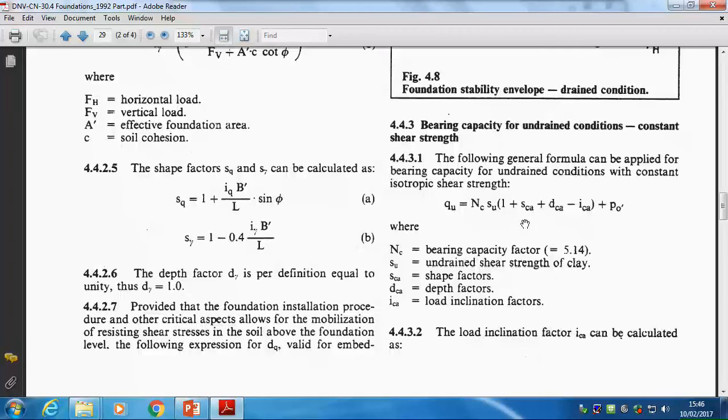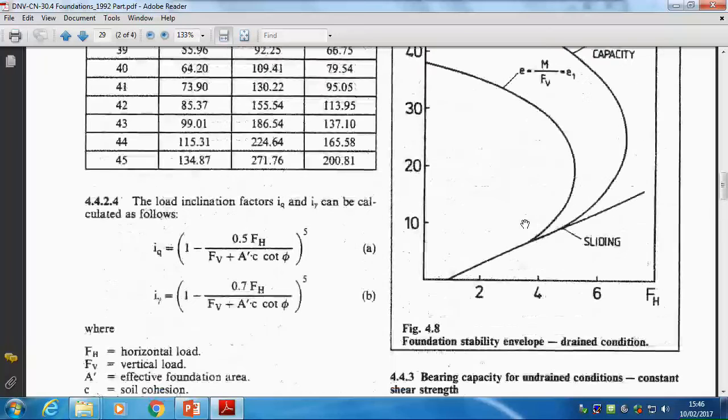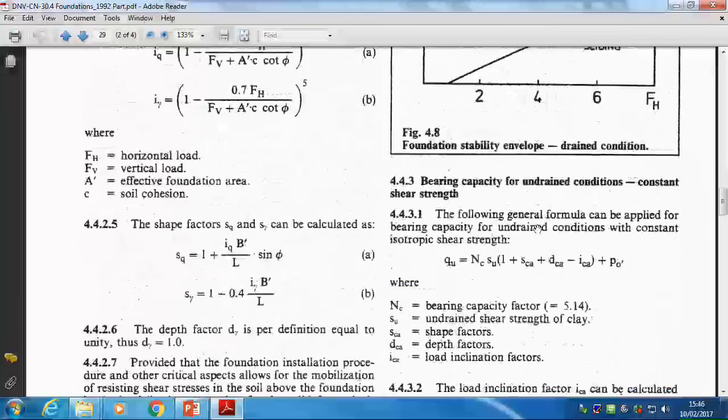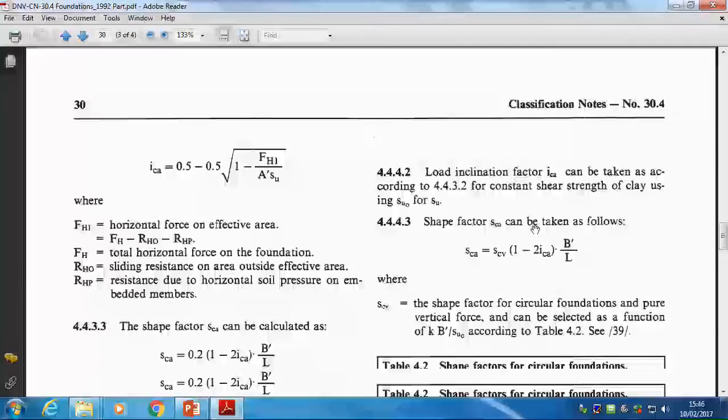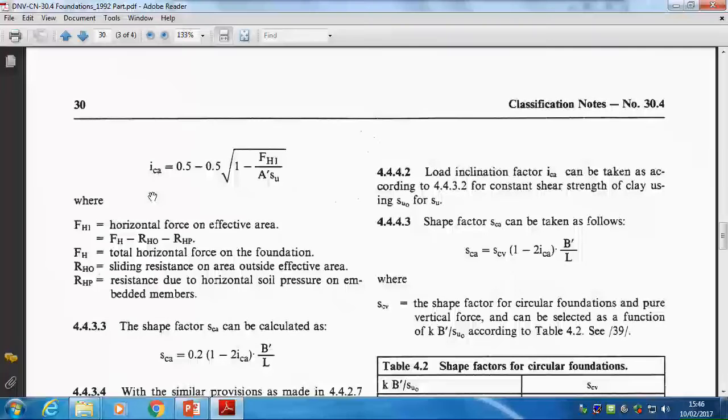If we assume most seabed structures are with no skirts, they land on the seabed, no depth of embedment. Okay, so in this case that would equal 0 if we're talking about a structure which is not embedded into the seabed. And then ICA equals the value, where is it? ICA is that value which you've said equals 0.5, haven't we? Sorry, 0, because this bit effectively cancels out.